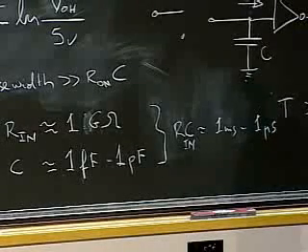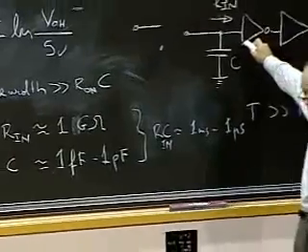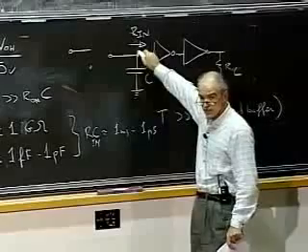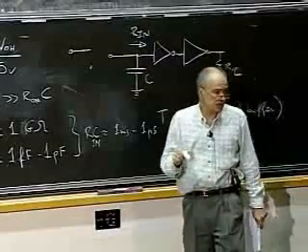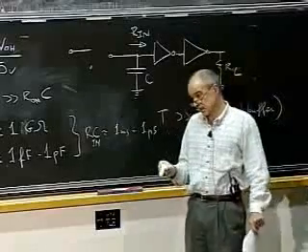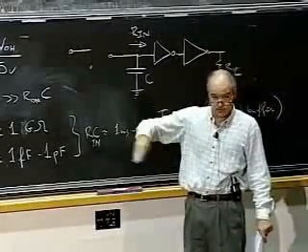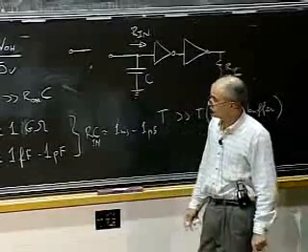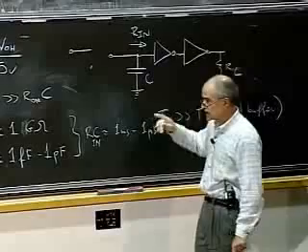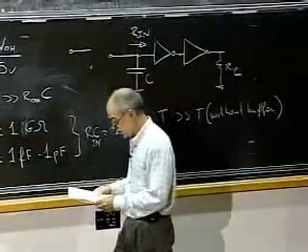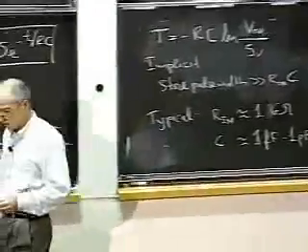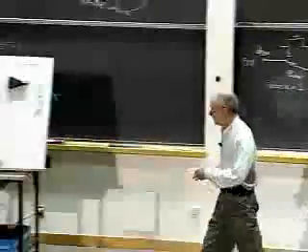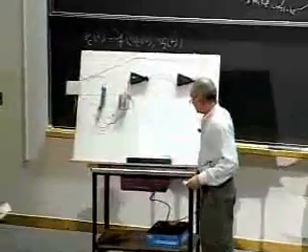So if I have this kind of circuit, somehow there's got to be additional circuitry that comes back, samples the voltage here, and restores it. And that's actually what is happening in the DRAM. And, you know, my laptop is working there, and its DRAM keeps getting refreshed every, say, a millisecond or whatever the condition is. Okay? But in our case, we're going to do a slightly different case in which we will create a static memory.